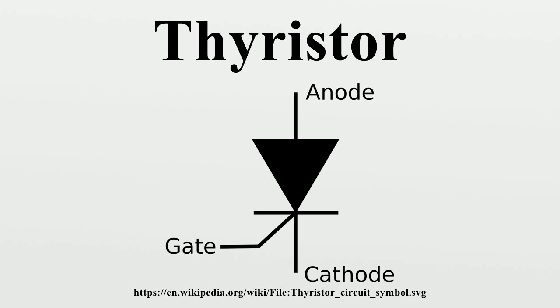Thyristors are arranged into a diode bridge circuit, and to reduce harmonics are connected in series to form a 12-pulse converter. Each thyristor is cooled with deionized water, and the entire arrangement becomes one of multiple identical modules forming a layer in a multi-layer valve stack called a quadruple valve. Three such stacks are typically mounted on the floor or hung from the ceiling of the valve hall of a long-distance transmission facility.